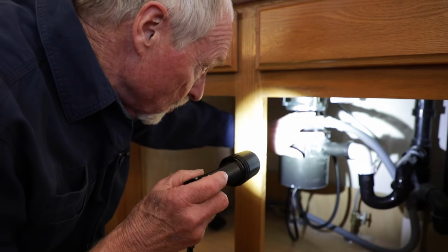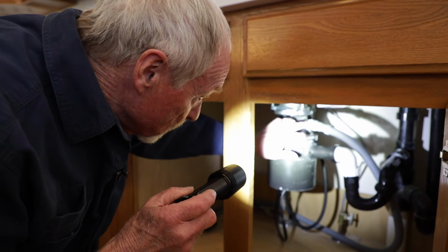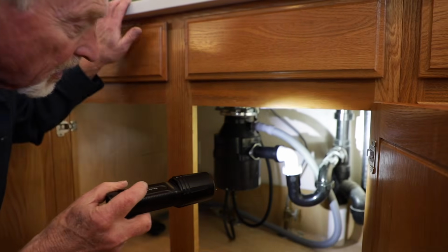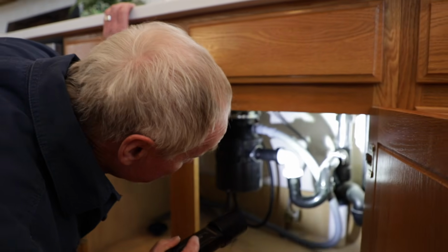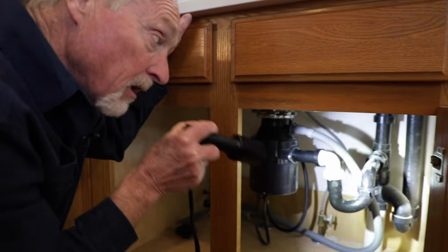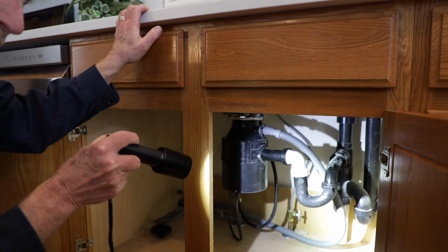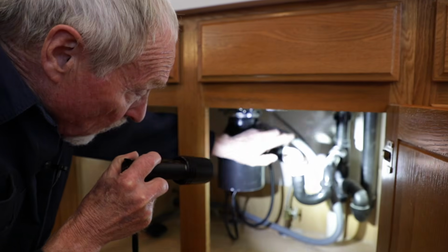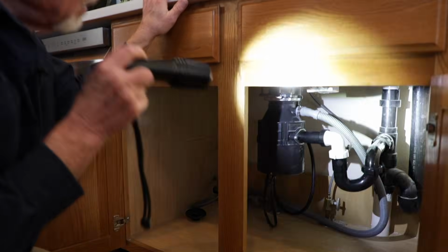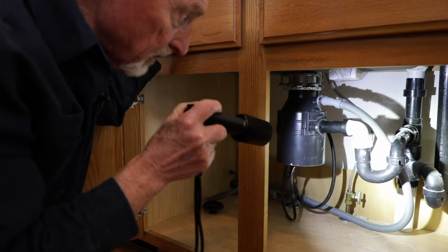In some areas, some jurisdictions, municipalities flat out say you can't hook the dishwasher discharge into the disposal if you have the alternative drain set up there. So in this case, it's certainly the best practice and smart. For one thing, that P-trap that we see there can dry out, and we can get sewer gases leaking into this kitchen. With the discharge going into the discharge vent here, as it should be done, that would keep the P-trap full of water and prevent sewer gases from backing into the house.